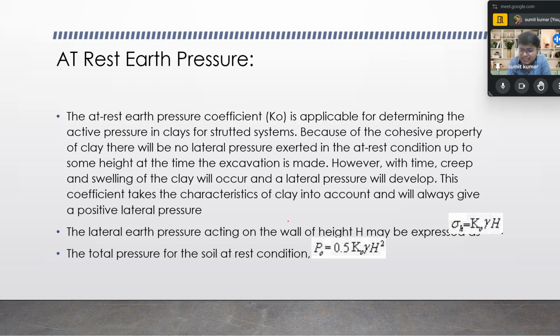This coefficient takes the characteristics of the clay into account and will always give positive lateral earth pressure. The lateral earth pressure acting on the wall of height h may be expressed as sigma h equal to K naught gamma h. The total pressure of the soil at rest condition is 1 by 2 K naught gamma h square, and how it takes place also needs to be understood very well.